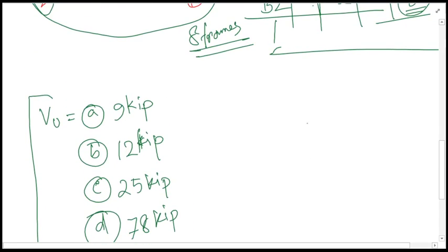So what is our concept here? Our concept in this case is very clear. That is, the total shear force, that is the VU, will actually be taken by the shear force taken by the steel, the shear reinforcement, and the shear force taken by the concrete.